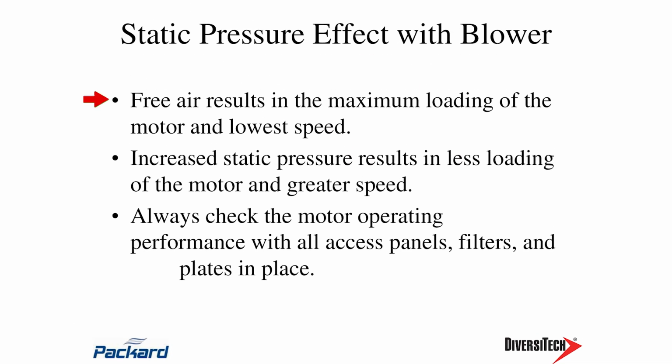Well, when I ran that fan blade in free air, weren't my amps low, the least load on it? So I'm trying to do more work. Now what that blower is doing, it's taking the air that is available to it, and if I'm running it in here, it has all this air that is available to it. And it's trying to take all of this air into its little inlet, change the direction of it, and pressurize that air. That thing's going to work as hard as it can.